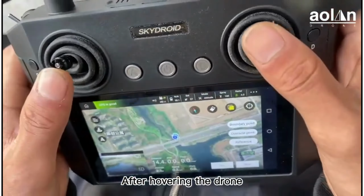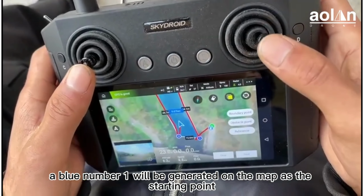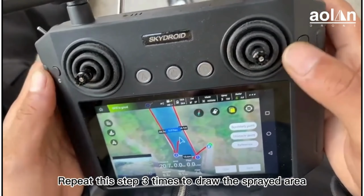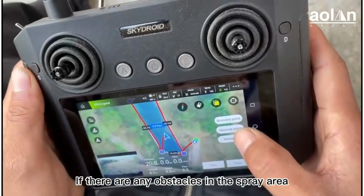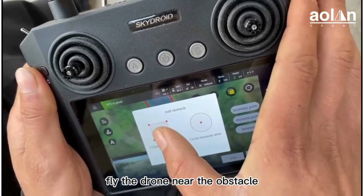After hovering the drone, click Add Boundary Point. At this time, a blue number 1 will be generated on the map at the starting point. Repeat this step 3 times to draw the sprayed area. If there are any obstacles in the spray area, fly the drone near the obstacle.